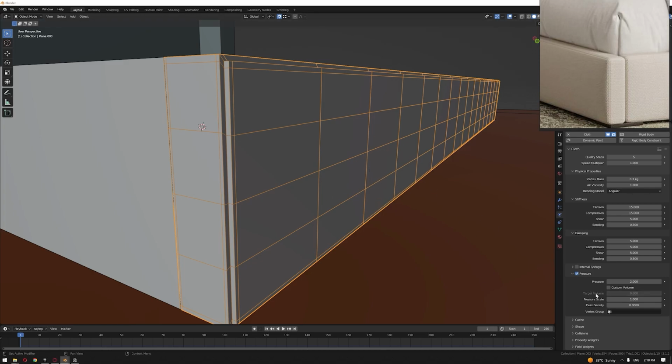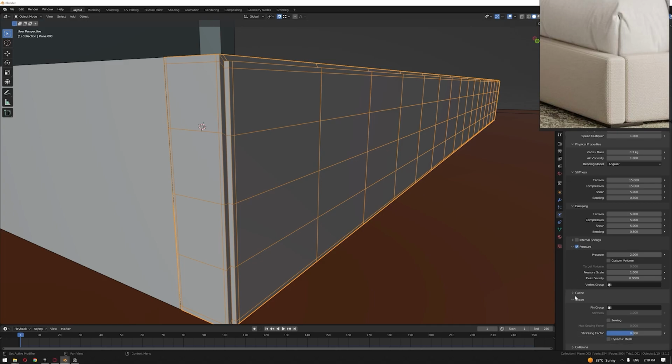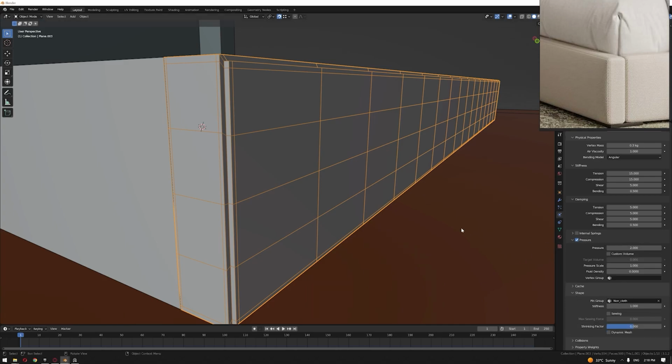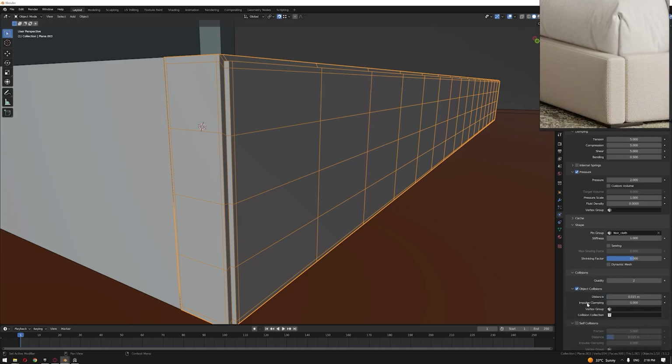inside, and to make sure also that inside the shape we don't wanna affect the vertex group that we have set up. And the occlusion, we'll set the distance to the minimum, so put this 0.0 to set it to the minimum, and we're gonna have a collision happening with these 3 all together.